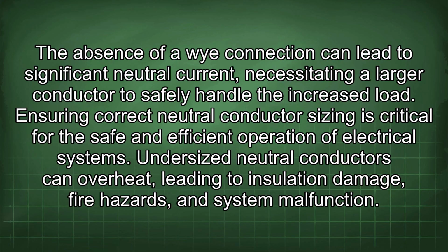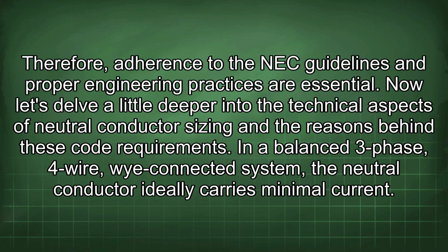Undersized neutral conductors can overheat, leading to insulation damage, fire hazards, and system malfunction. Therefore, adherence to the NEC guidelines and proper engineering practices are essential. Now let's delve a little deeper into the technical aspects of neutral conductor sizing and the reasons behind these code requirements. In a balanced three-phase, four-wire, wye-connected system, the neutral conductor ideally carries minimal current.